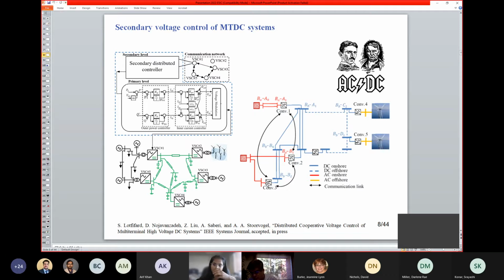In a centralized setup, you have one controller at the top communicating individually, using a radial, star communication system with each inverter. If that centralized controller fails, everything fails, or if the communication to it fails. But if you distribute that leader to several points, not just one point, you can have as many leaders as you want.